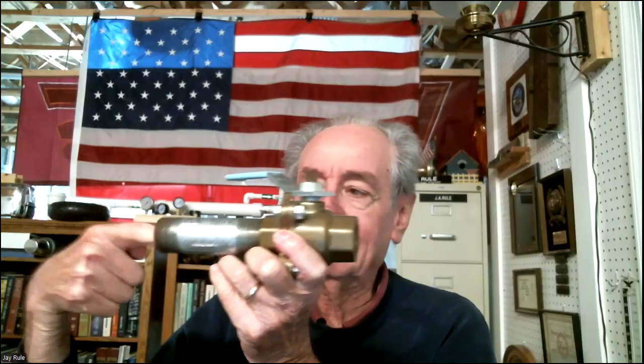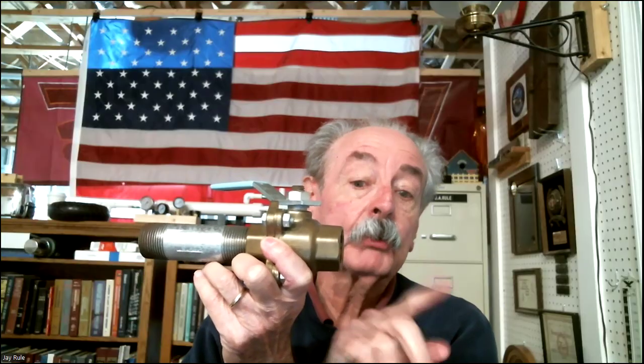If this is the inlet, the pressure would be high, and coming out here, the pressure would be lower in this partial position. That's what we call a throttling valve. A ball valve is a throttling valve. It throttles the flow. It enables us engineers and operations people to adjust the mass flow rate going through a valve at the expense of pressure drop.